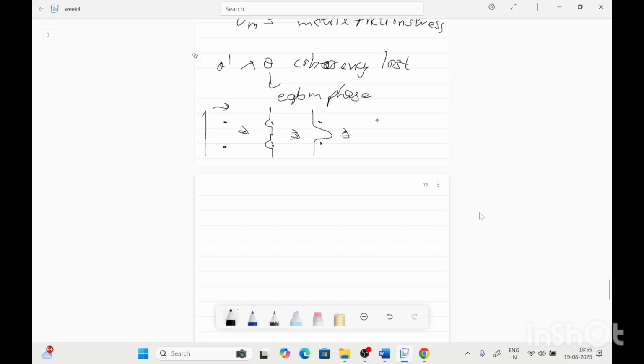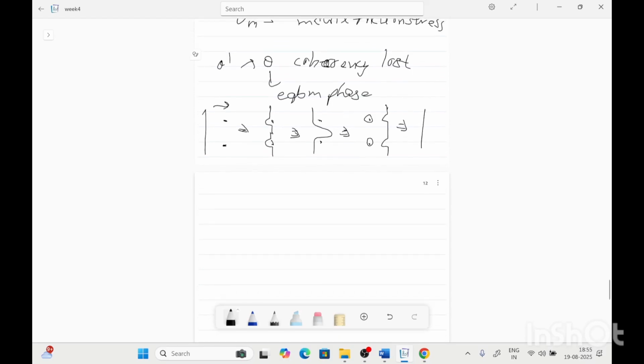Then after some point, the dislocation loop is generated on the precipitate and the dislocation line will form like this. And after some point, it will straighten out. The dislocation straightening out is because of the surface tension at these points. So due to the surface tension, the dislocation will straighten out after some time.